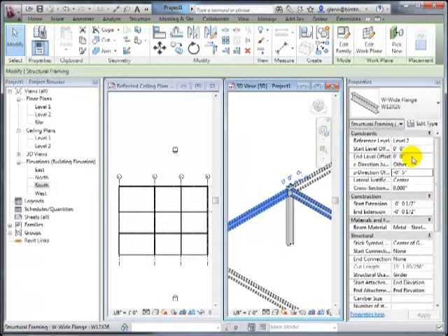If you define the beams as going from the end of the column to the end of the column, if you were to add an offset, would that affect it? Or does the floor level govern where the beams go? The beams are placed relative to, well, it starts with level 1 or 2, and then with the offset. So there's sort of a hierarchy to what it does.